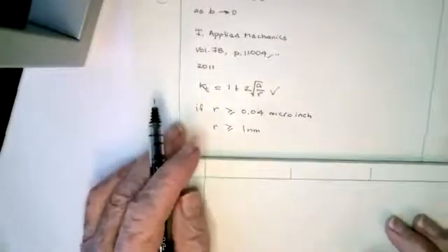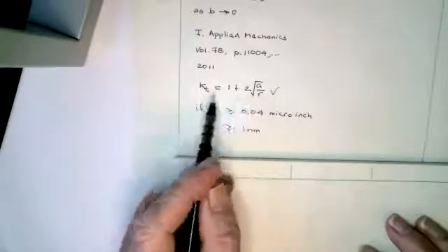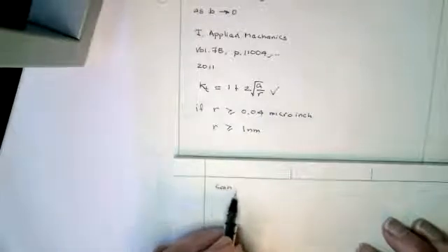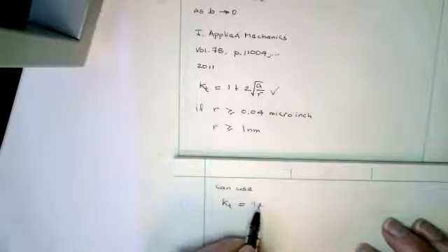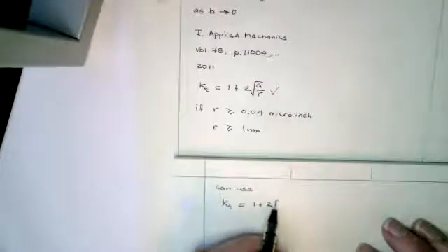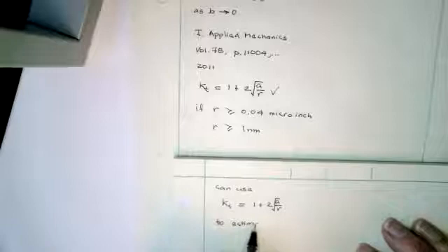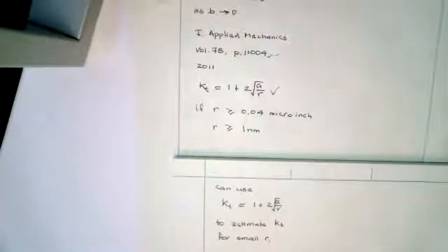This is going to apply for pretty much any radii you look at. Actually, when you get inside this radii, the stress concentration starts going down and eventually goes down completely, and the crack is closed. But you can use that formula to estimate KT for small r.